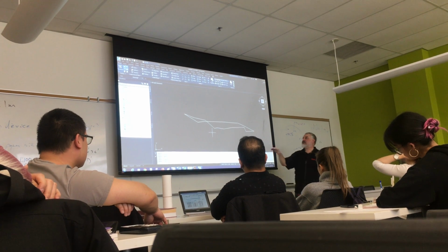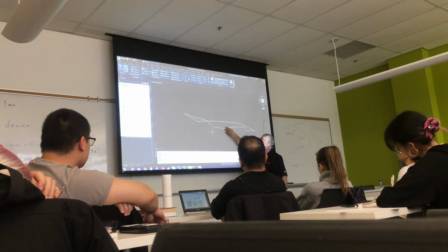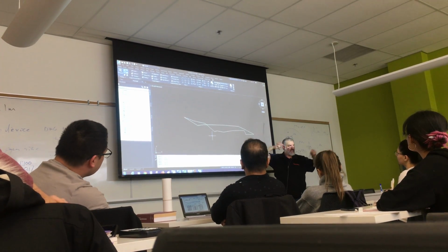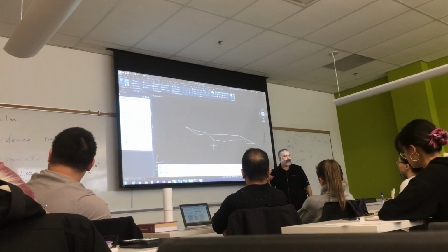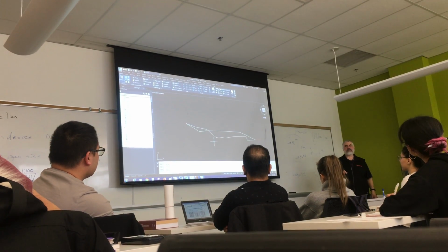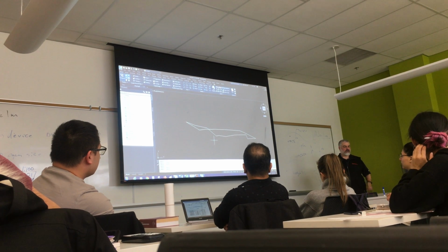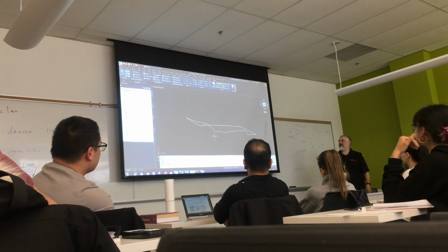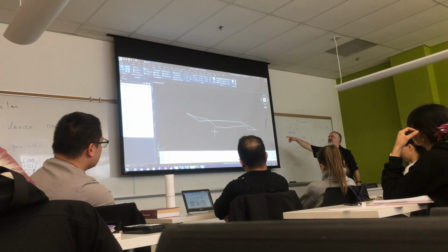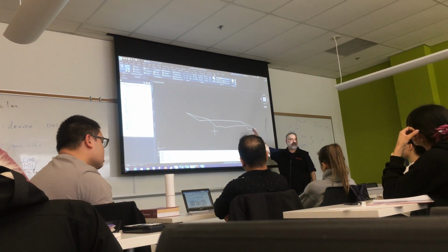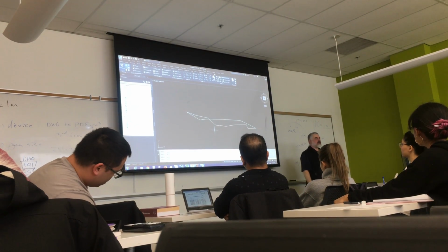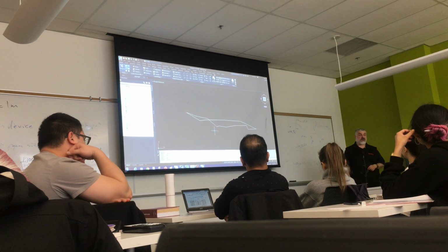Okay? Now, if there's some cut here and then fill in the middle and some more cut here, if you have two separate areas that represent cut, add them together. Total cut, total fill. Okay? Any questions about that? Total cut, total fill. All right. And then all the annotation that we talked about, right? I don't need to see the polyline that you drew, right? Just do it off to the side, get the number, put the text on the drawing. And that's good.